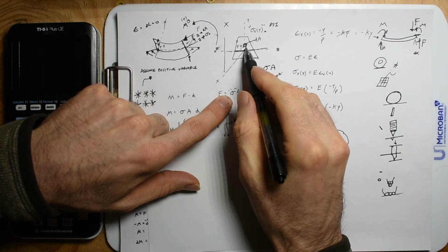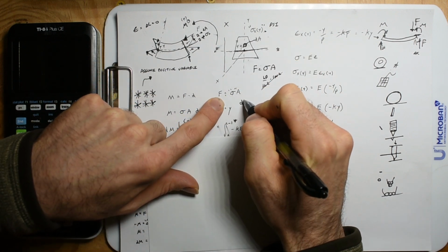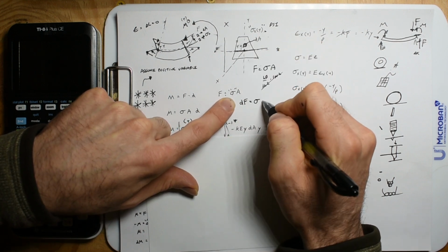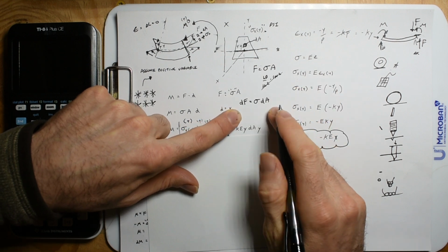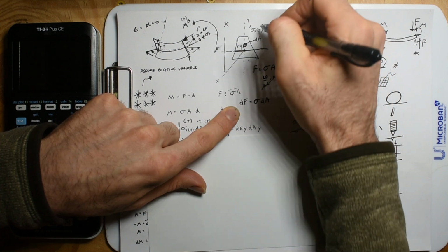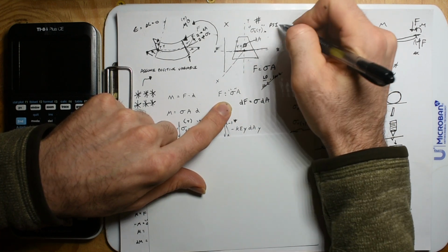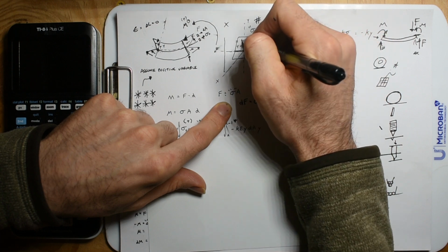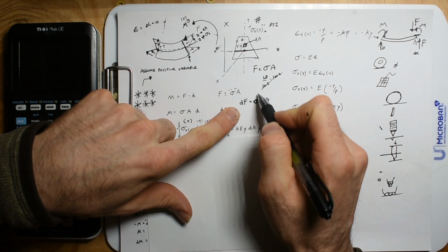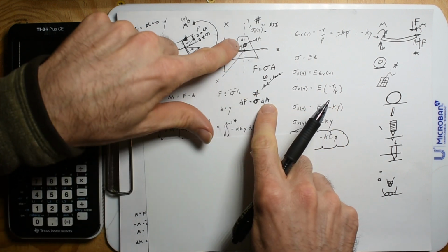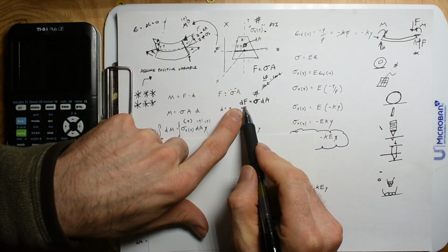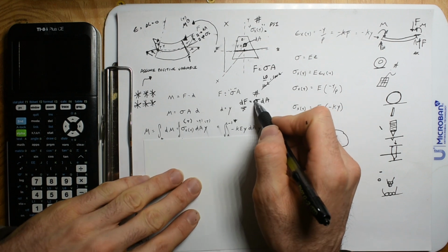That stress times that little chunk of area. So now we can do a derivative. A tiny little force is equal to the stress times the little area. I think the hardest thing with derivatives is what gets a d. This stress is a number, that PSI value doesn't change just because we have a tinier area. So this value is unchanging, but the area is real small, and then we're getting a small force. So little dF is equal to sigma dA, stress dA.